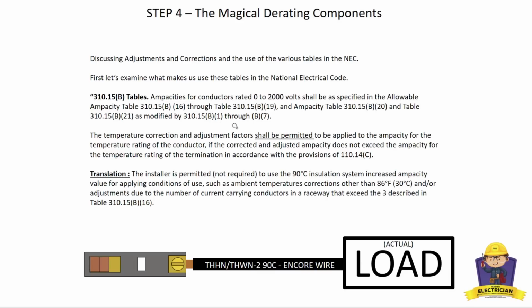But we also have 310.15(B)(3)(a), the number of conductors. (B)(2)(a) is the ambient, that falls in here. (B)(5) is going to deal with, I think, the neutral conductor. (B)(6) deals with the grounding and bonding type conductors that don't have to be counted and things like that. So anyway, this just shows you that all the tables correlate together.